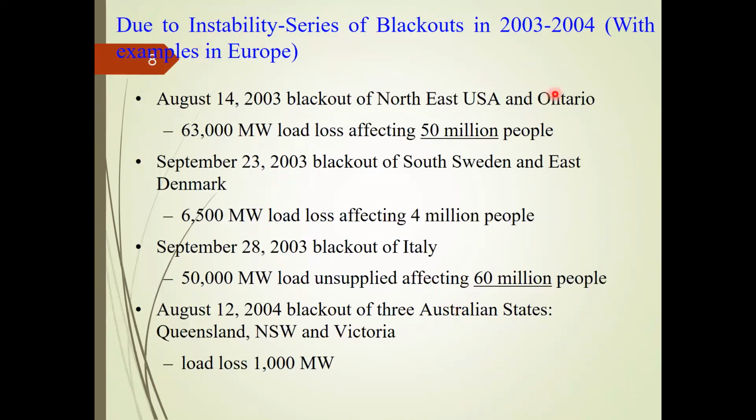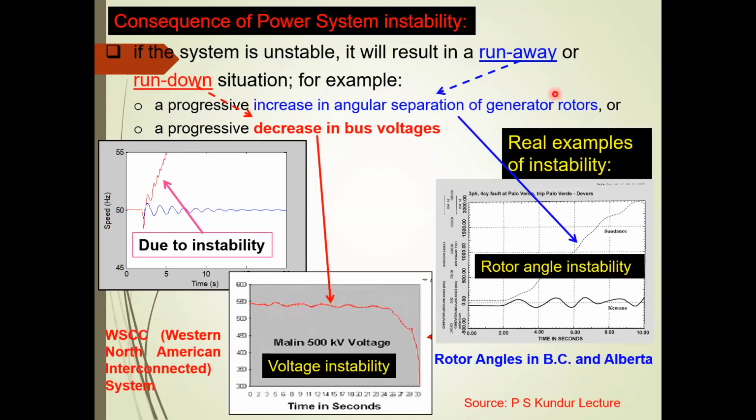Hello, Prof. Yes, please, if we go back again to that same previous slide. You make mention of relays that are used in sensing the instability. I want to ask, is there a specific number of seconds? Take, for instance, some disturbances could just be transient and it will restore back to its stable state. Is there a specific number of seconds that the relay has to track before it trips in order to protect the generators or the equipment?